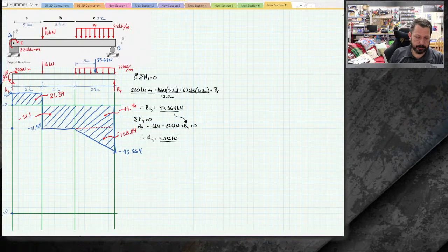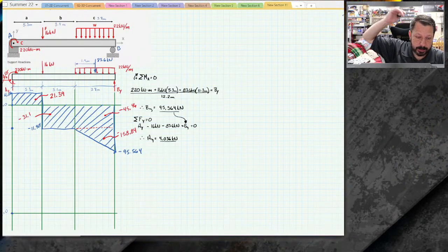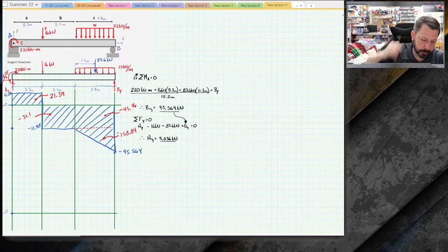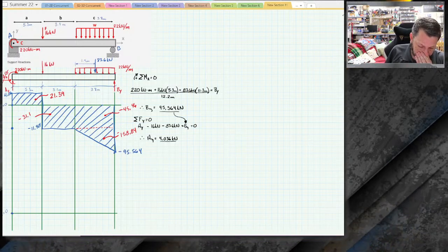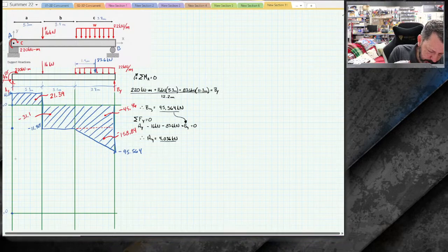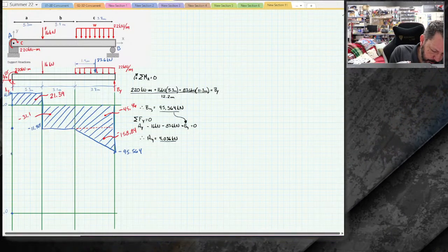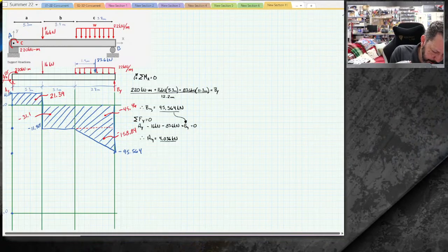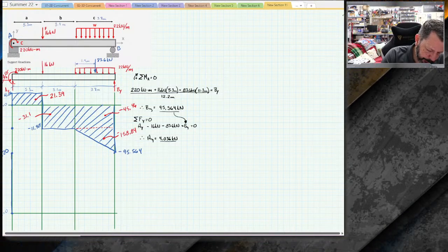220 kilonewton meters. So the very first thing that happens is we immediately go up like a step change, just like a point load in the shear diagrams. We go up by 220 kilonewton meters. We were at 0 kilonewton meters, so plus 220. Let's see what's reasonable. I want it to be maybe up here for 220. Yeah, 220. So we go straight up to there first.